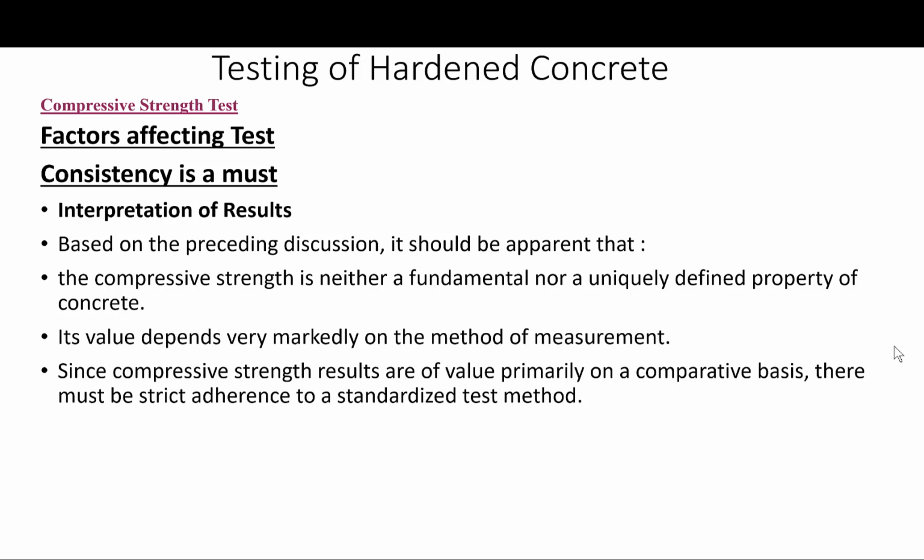Based on the preceding discussion, it should be apparent that the compressive strength is neither a fundamental nor a uniquely defined property of the concrete. Its value depends very markedly on the method of measurement. Since compressive strength results are of value primarily on a comparative basis, there must be strict adherence to a standardized testing method.